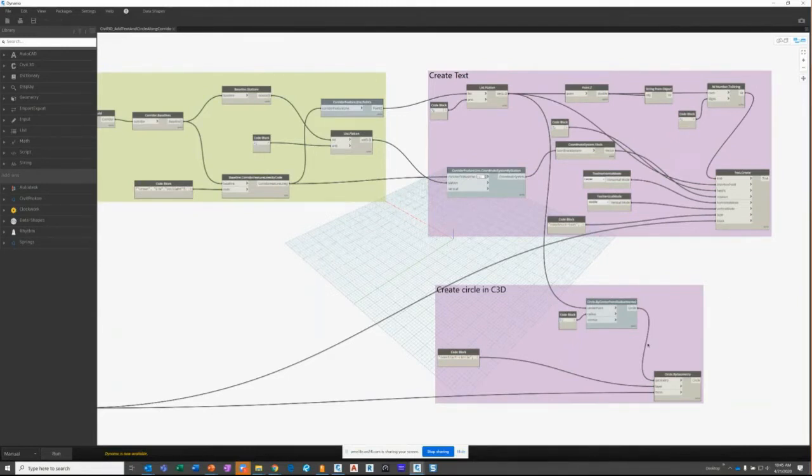And I've seen people using Dynamo to place sidewalk curb cut ramps into their corridor and build them that way. You can use them to automatically place text and update text within your corridor for elevations, etc., which is what I'm going to show you today. And it's a really quick, easy way to rerun and replace that text as your data updates.